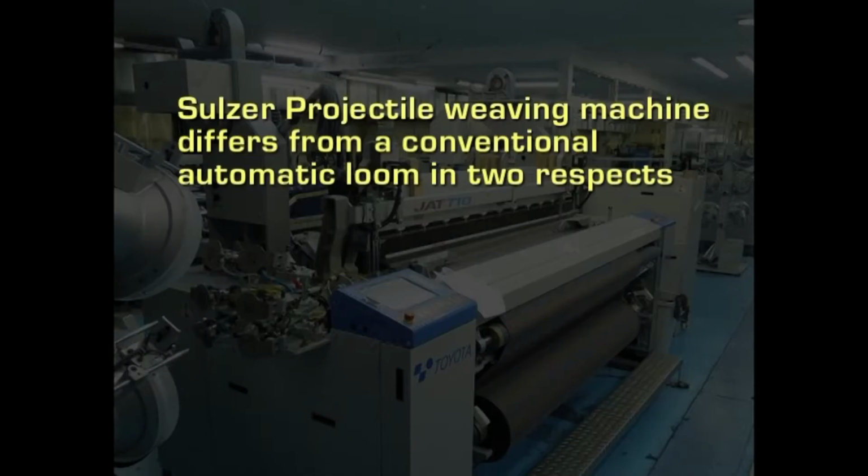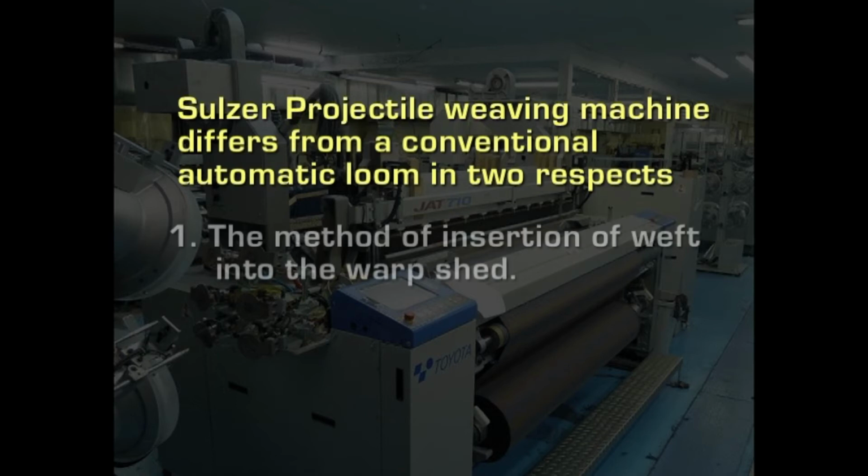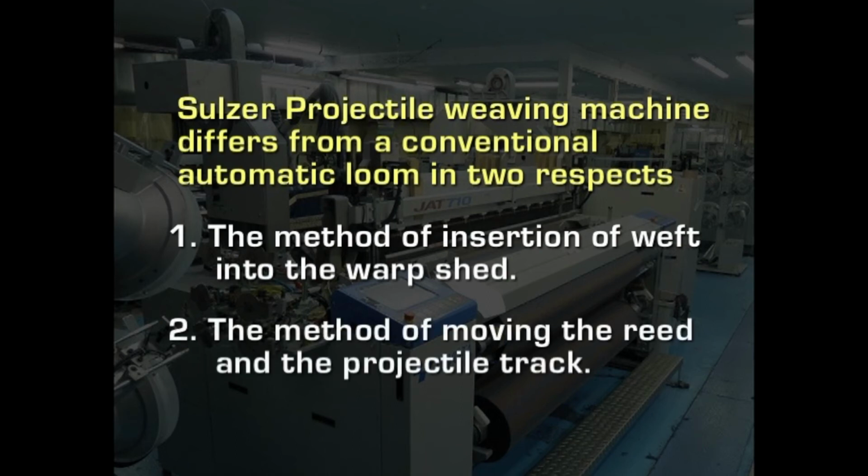A metal torsion rod propels the projectile, accelerating it through the shed at the moment of picking by means of a picking mechanism. The Sulzer projectile weaving machine differs from a conventional automatic loom in two aspects: the method of insertion of weft into the warp shed and the method of moving the reed and the projectile track.